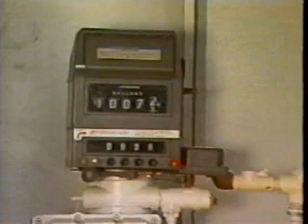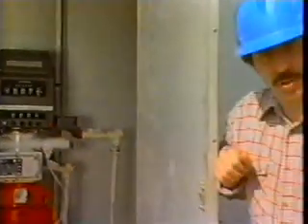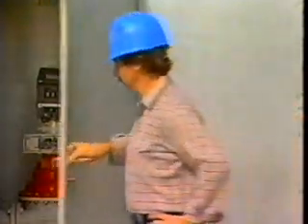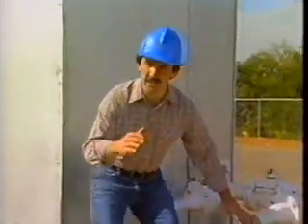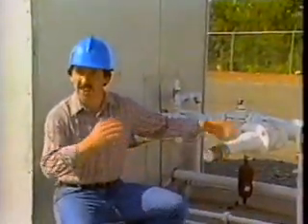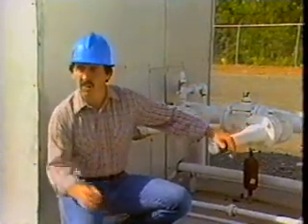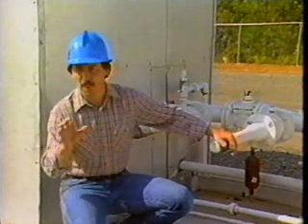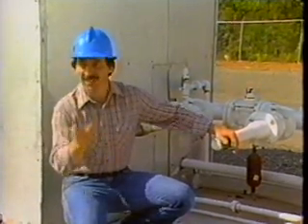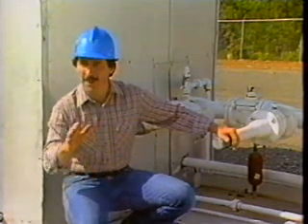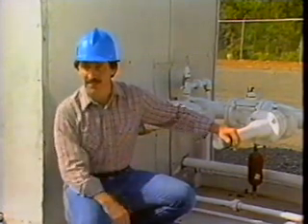Liquid meter proving is the physical testing of the performance of a meter that is in service, measuring the flow or volume of a stream. The meter proof is performed by placing a meter in series with a meter prover, which has a known base volume for standard conditions. The prover is installed so that during a test run, all product measured by the prover is also measured by the meter. Alternately, only the product measured by the meter is measured by the prover.